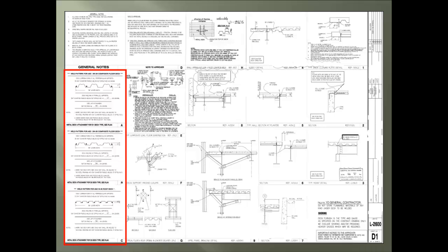As we move down the sheet, we find the next 3 details cover the attachments of the 3 different types of metal decking provided for the project. And notice the hat height which separates the different types. We now see a special note to the approver of these drawings, which usually is the design professional team. The first X is the detail covering a typical composite concrete floor construction.